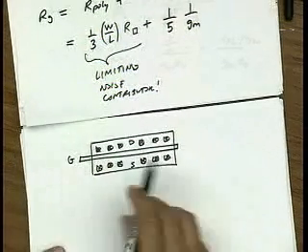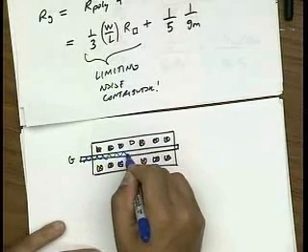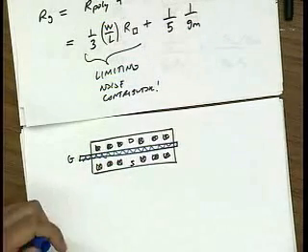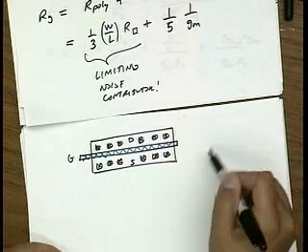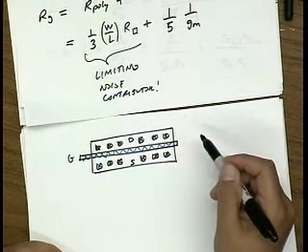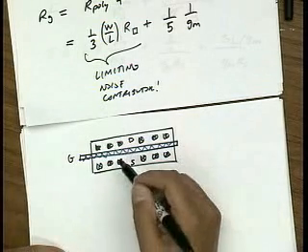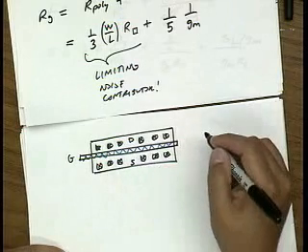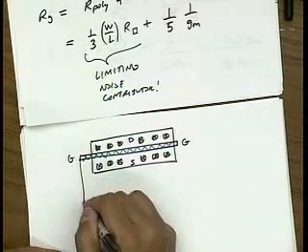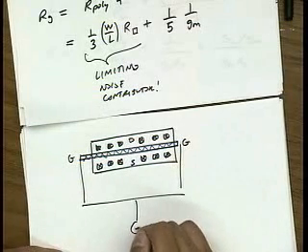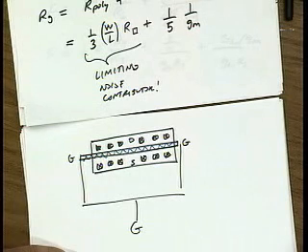And so we can see that this resistance is simply this series resistance times 1/3. Okay? And it turns out that if you double contact it, which we talked about a few lectures back, you can reduce this resistance down by a factor of 4. So I could put another gate contact here, so I could have my signal coming in on both sides like this. This is the double contact. That helps. Reduce it by a factor of 4.